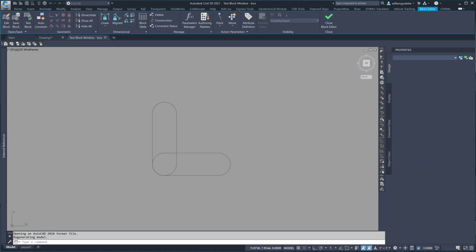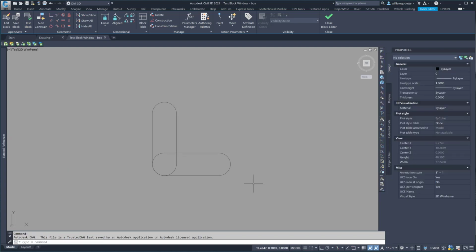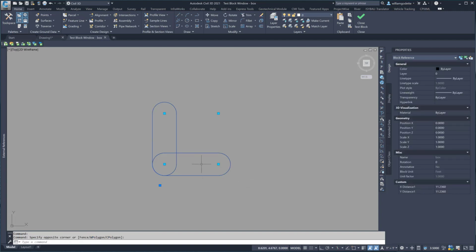So what happens is that if we grip this, we'll notice we have 4 grips. One thing that allows us to do is that we have this grip going on here, and we can turn our ortho on, and so now I'm stretching this one edge out, right? That's cool. I can pick this grip and it stretches this edge out. That's neat also. This grip here, if we pick this grip, I can stretch it up this way or I can stretch it out this way. If I turn ortho on, depending on where I put it, both of those move independently.